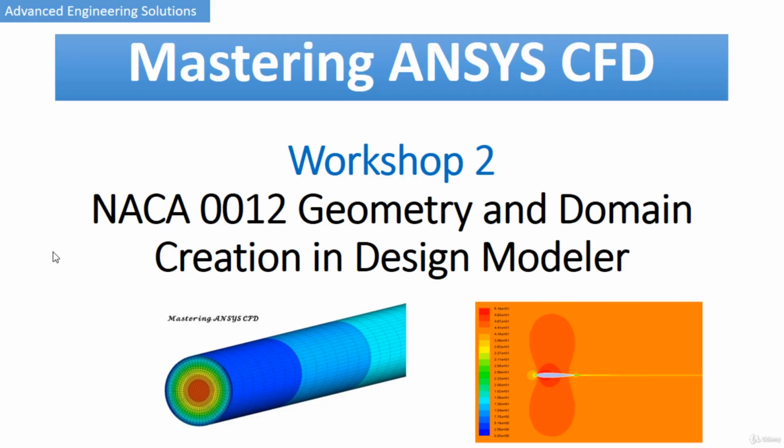This is the second workshop, and the title of this workshop is the NACA 0012 Airfoil Geometry and Domain Creation in the Ansys Design Modeler. The method I am teaching you is generic, so you can apply it to any airfoil geometry, and the domain creation for 2D cases is again generic, so you can apply it even to cases other than airfoils.